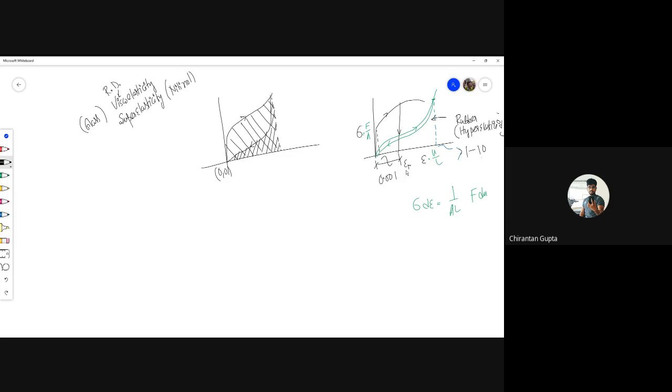Like in the rubber band, let's say, if we are talking about a rubber band. In a rubber band, you can see the loading and unloading curves are really close, so more or less the energy is conserved, the mechanical form of the energy is conserved. And the answer to that other question of yours is pretty low hanging fruit. What happens to any form of mechanical energy that is being lost? What happens to that? It's in the form of heat.